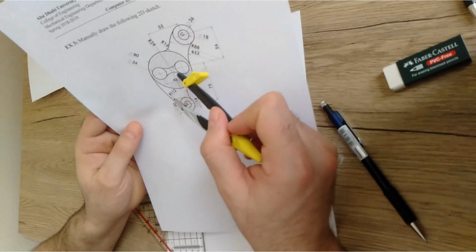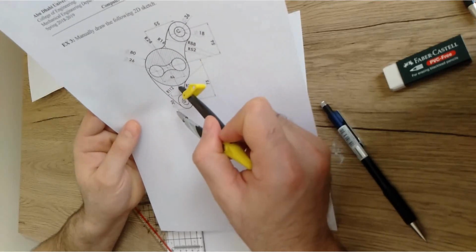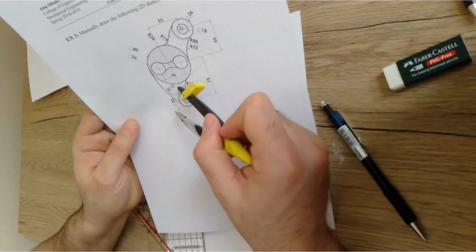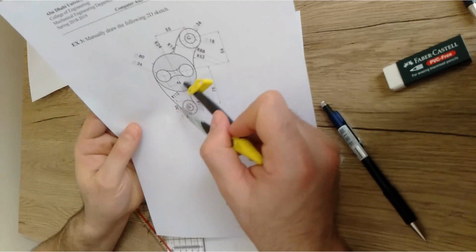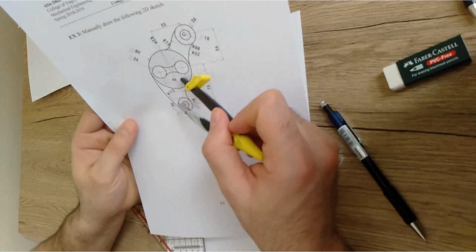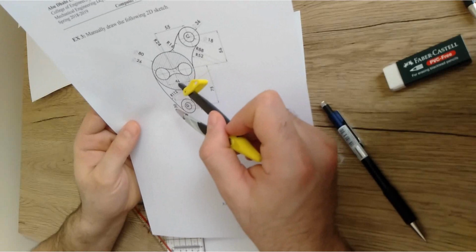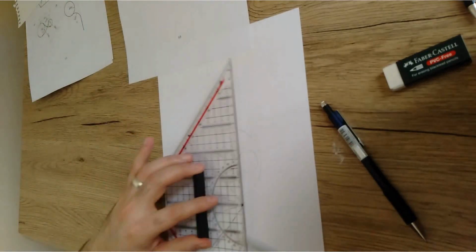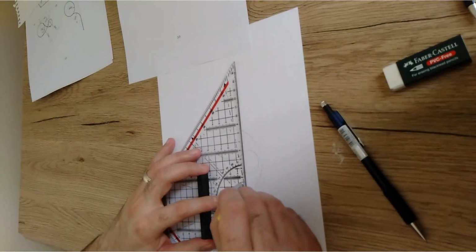And since it is identical, even if you try to move from this center to this center, we're going to go over the tangent point. It means that we are going to sum the radius, so it's going to be 13 plus 24. So we're going to open the canvas again by this 37.